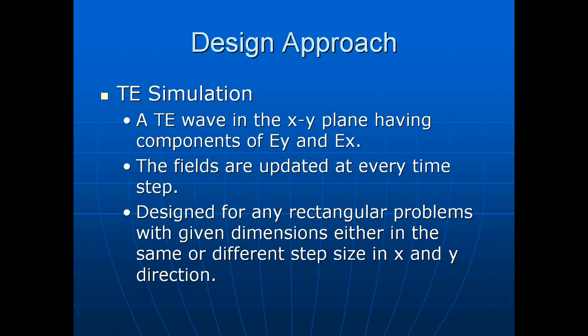The E and H fields are updated every full time step by using the difference form of Maxwell's curl equation. A perfect electric conductor is chosen as the source, which is located at the center of the domain. The type of source can be questionable depending on what the analyst is using. Other types of sources are sinusoidal, Gaussian, and impulse. The source is available in 4 standard forms: unit time step, impulse, Gaussian, or sinusoidal.